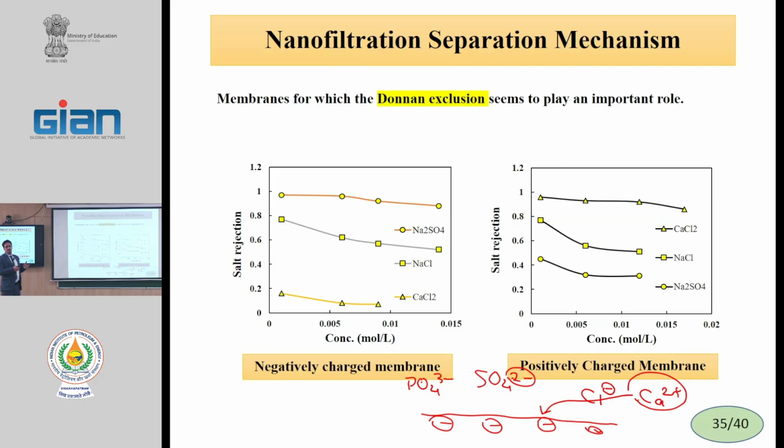Usually the wastewater pH is between 6 and 8, and when we say negative charge or positive charge, we refer to this range. For positive charge, we usually use amine groups. For negative charge, we use hydroxyl, carboxylic, or carbonyl groups; OH groups can give a very low negative charge.